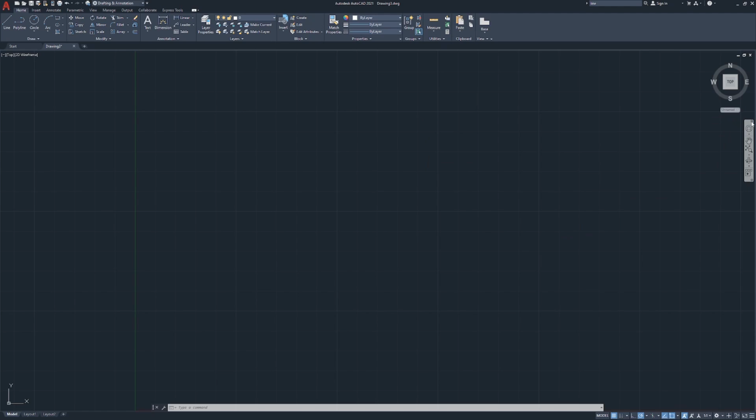So like I said, I typically close this. I'm going to click that little tiny X in the corner. Just get it out of the way, because you're going to hit it accidentally. 9 times out of 10, you're not going to need it. Zoom extents is great, but if you're zoomed in, let's zoom way in. If you double click your mouse wheel, that's zoom extents. So now you have zoom out, zoom in, pan, double click mouse wheel, zoom extents. You don't even need that little panel over on the side. Turn it off.